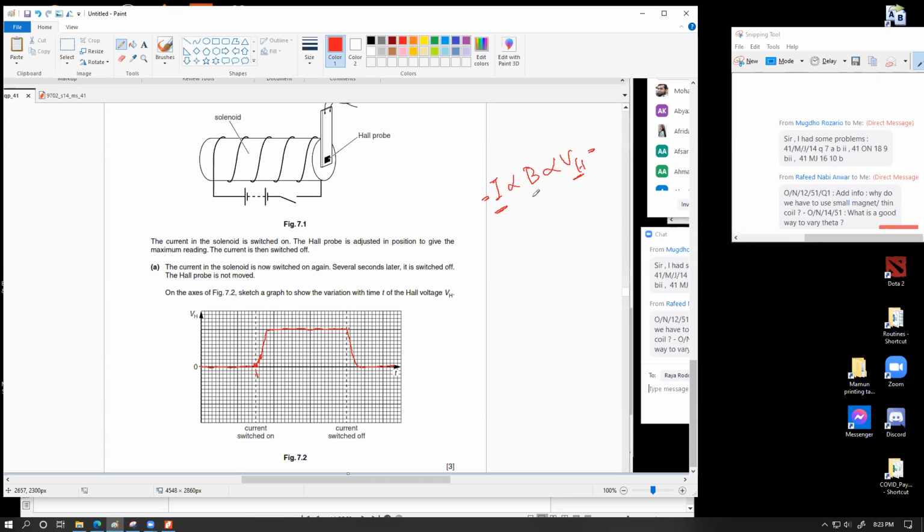Sir, I did the same thing, but the rise you showed took some time. I assumed it would be instantaneous, as in I showed a vertical line. But that's the precise thing that you shouldn't do. Showing a vertical line would mean that irrespective of the scale of this time axis, whether it is in hours or picoseconds, there would be an instantaneous rise of voltage. The voltage will not rise instantaneously, because for the current to rise from 0 ampere to the optimum peak ampere value, it will always take some time.